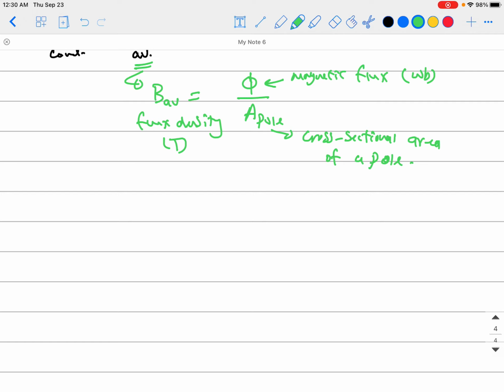Okay, so doing the same idea now, how to calculate the cross-sectional area of the pole, A pole? Easy. You're talking about a cylinder. The stator is a cylinder, like we said before. The rotor is a cylinder and the stator is a cylinder. So that is the side area of the cylinder, 2 pi R L, divided by P. What is 2 pi R L?